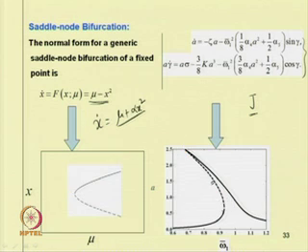As it is unstable at this position, when one sweeps up the frequency, at this position the system will show a jump up phenomenon, and with further increase in frequency it will follow this path. Similarly, during sweeping down, that means if you decrease the frequency, one can follow this path, and at this point it will jump down. So, one can observe this jump up and jump down phenomena at these bifurcation points.